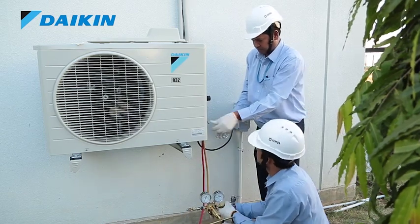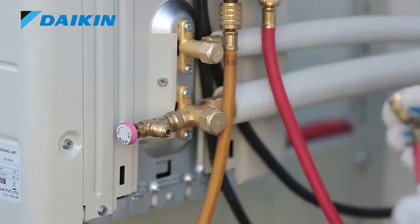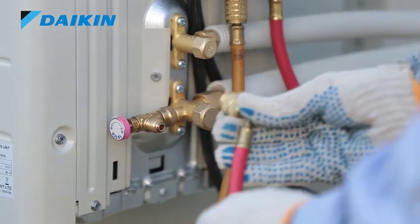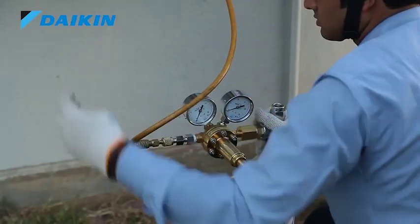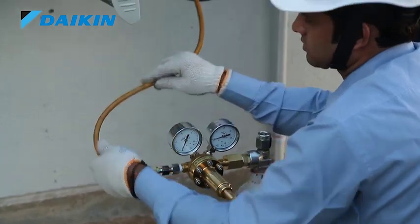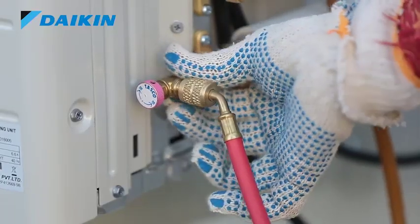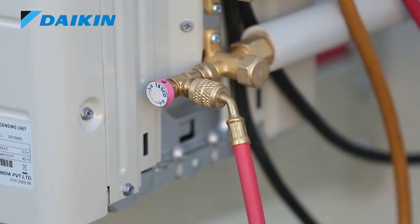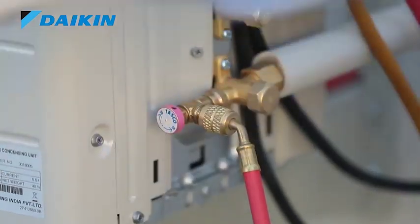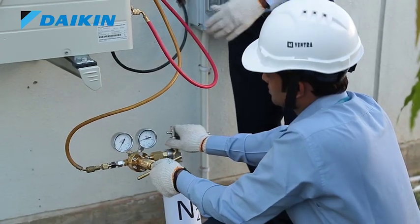Connect the nitrogen cylinder with the outdoor unit using a gauge manifold and apply nitrogen up to the test pressure.